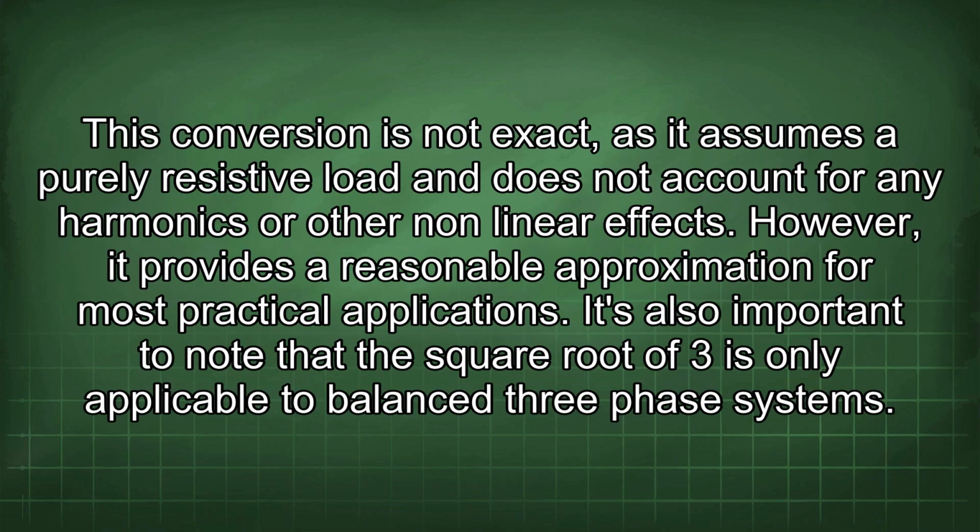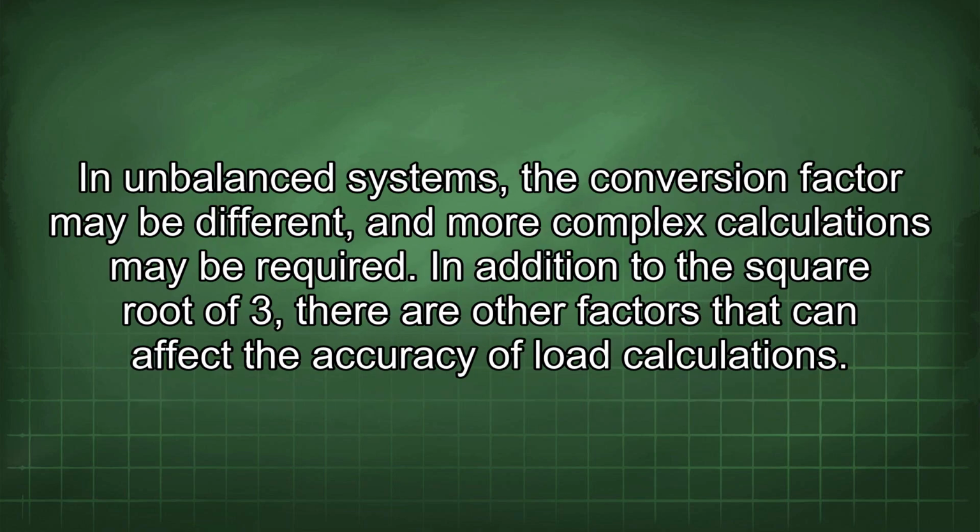This conversion is not exact, as it assumes a purely resistive load and does not account for any harmonics or other nonlinear effects. However, it provides a reasonable approximation for most practical applications. It's also important to note that the square root of 3 is only applicable to balanced three-phase systems. In imbalanced systems, the conversion factor may be different, and more complex calculations may be required.